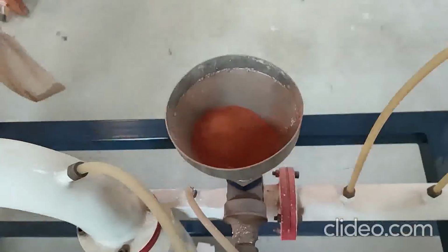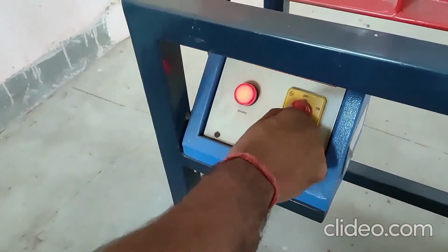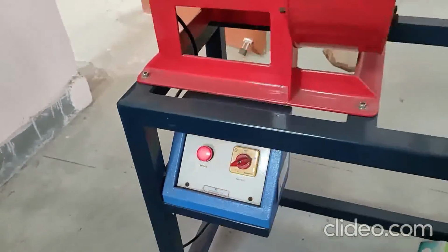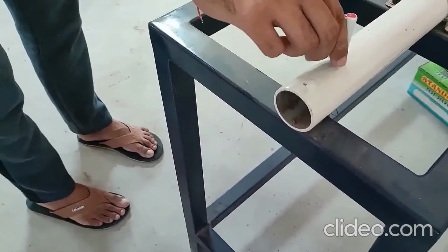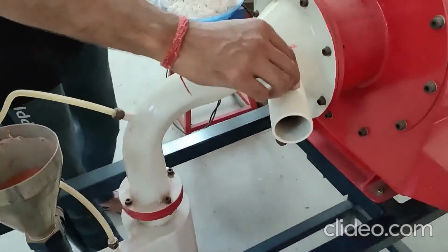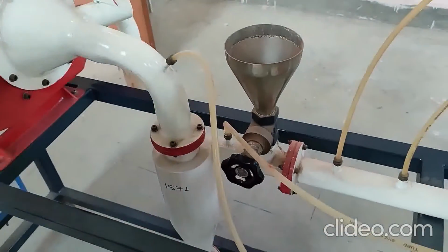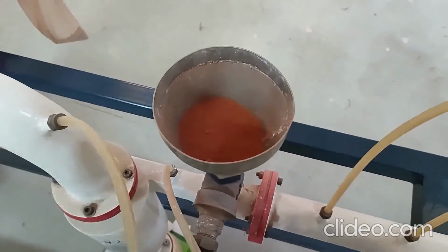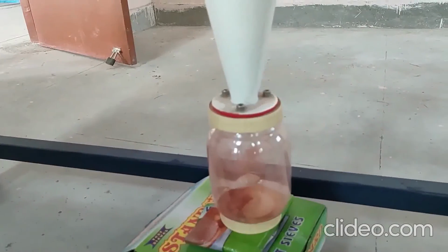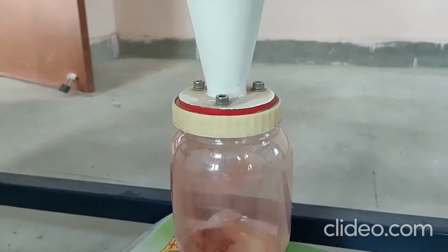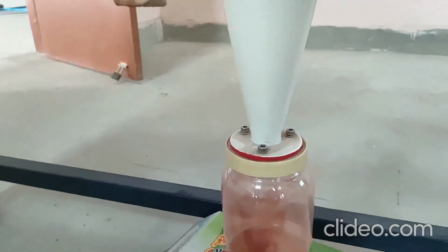Now after putting the feed in the feedstock section, we will switch on the main power supply and the air blower respectively. Now the cyclone separator equipment is in action, and we will partially open the bypass valve and the flow control valve. So now after opening the regulatory valve, the cyclone separator is separating the feed on the basis of its density, and the denser material is separated at the bottom of the separator in the outlet or the reject port, and the less dense or clean air is separated out from the upper section of the cyclone separator in the clean air section.